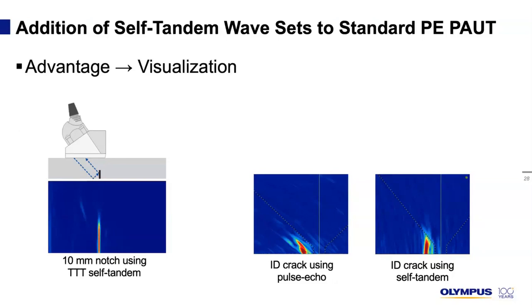It's just that the profile of the flaw, as we can see on the very right hand here, is more true to reality instead of the traditional corner trap and tip diffraction. That can be fairly easy to interpret for experienced users, but may appear as two separate flaws for beginners. So in the end, TFM just helps to remove that doubt when using the right waveset.